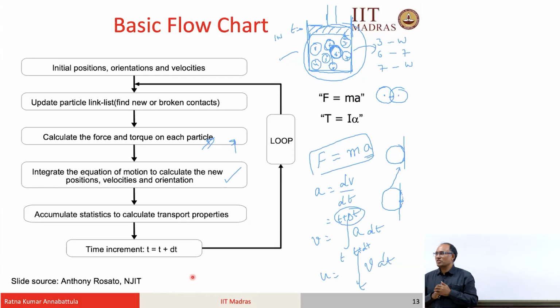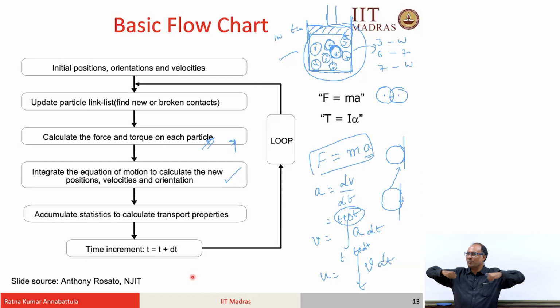It depends on the contact constitutive response. You should not allow a significantly high amount of overlap. It should be a smaller fraction of the radius of the particle to be realistic. So, depending upon the contact constitutive relation, you have to add a higher penalty so that you minimize the interpenetration. Imagine you are applying a force from this side, and these particles are pushing each other. This force increases significantly, and hence this is able to push them apart.